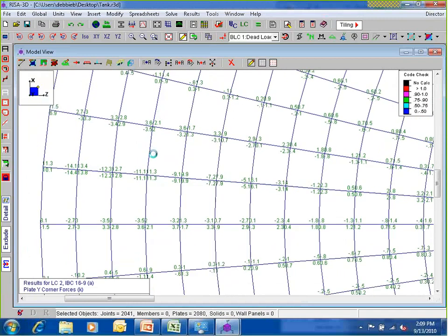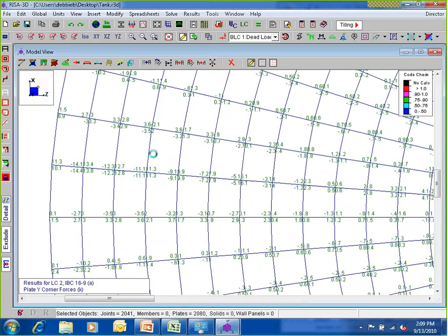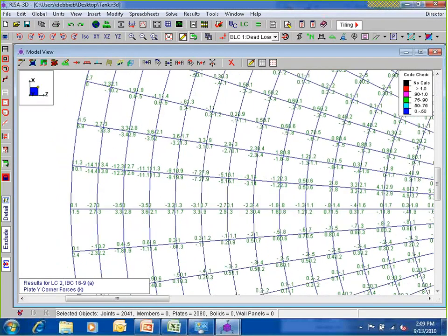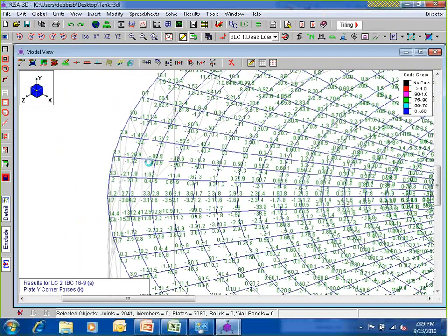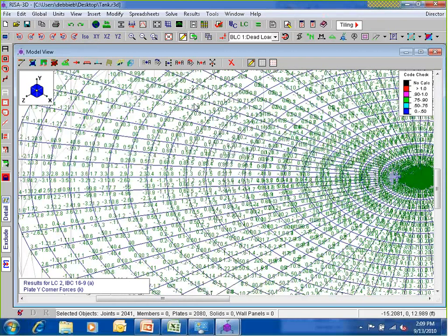So the internal force summation tool is a really important tool to use, but again, make sure you know it's based on what is selected. If I had other things selected in the model, it's going to cut an infinite plane along whatever is selected in my model. It will also make a difference if I made the view slanted, like an isometric view. That's going to give me different results, because you're basing it on a new local axis that you cut.